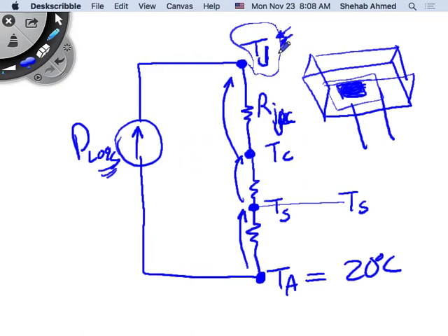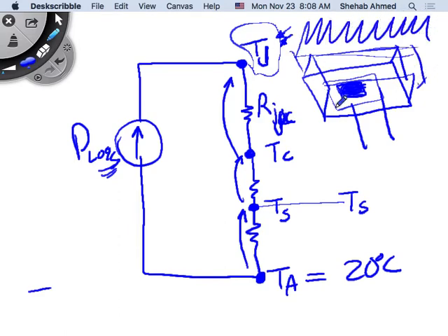So how do you come up with this value for this temperature? This temperature at the junction, again, the junction is basically the silicon junction of our actual physical die that's inside the package, right? This package can also be mounted on a heatsink if needed. If needed means if the junction temperature is too high, you will need to find a way to reduce it. So how do you reduce the junction temperature? We will find that we will have to reduce these drops.